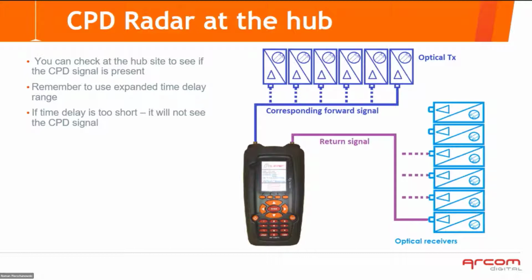When someone is troubleshooting intermittent CPD that was very high level at night, and now in the morning when he goes to work this event is not present, it's just a slightly elevated noise floor, searching for CPD is possible, but when you are 10 miles away from the fiber node, before you drive there, you can verify if it's present and it's searchable.